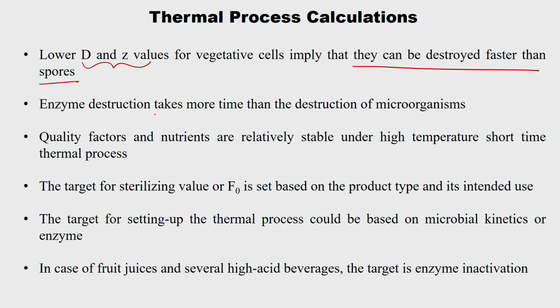Enzyme destruction takes more time than the destruction of microorganisms, because if the two are done at the same temperature for the same time, then we will not be able to maintain certain enzymes which are essential for the food quality. And quality factors and nutrients are relatively stable under a high temperature short time thermal process, HTST, that is what we most of the time follow, this HTST.